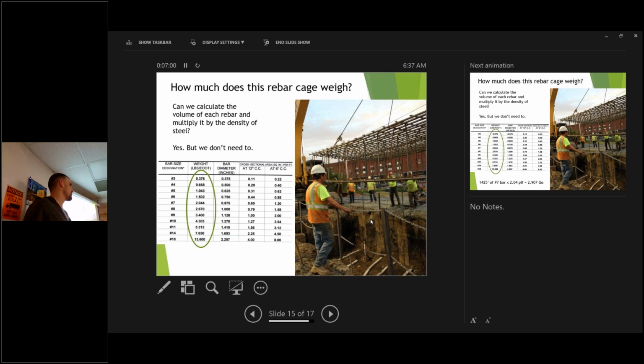And there's sheets on most of this stuff. You got a bunch of rebar, you got a bundle of rebar. Rebar's often bundled in 2,000-pound increments, but you can just figure it out. 5 bars, a pound a foot, 7 bars, 2 pounds a foot. Little tricks like this are really good to remember. So we don't want you shooting from the hip, but if you're out in the field without a lot of resources and you can do some quick math and remember the weights of some of these things, it can really help. That'd be a good one to have on an app too. I agree. Yeah, we can post the rebar. This basic rebar chart's good for lots of reasons. Yeah. We can post that one too.